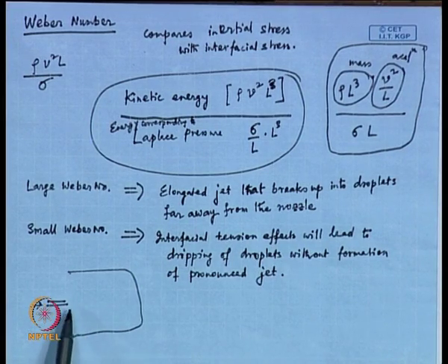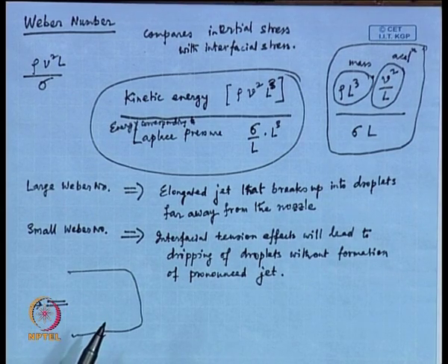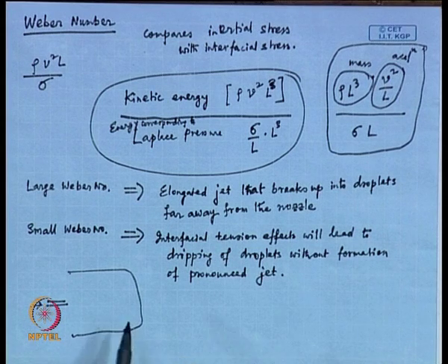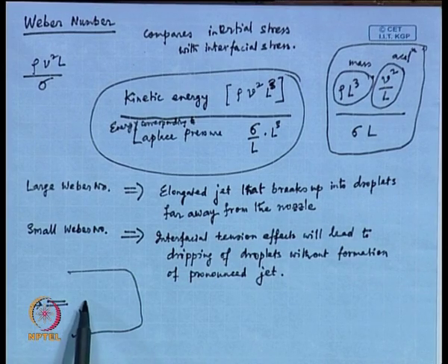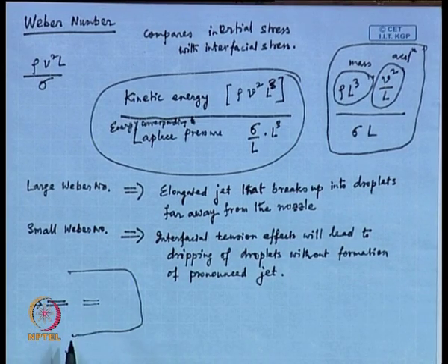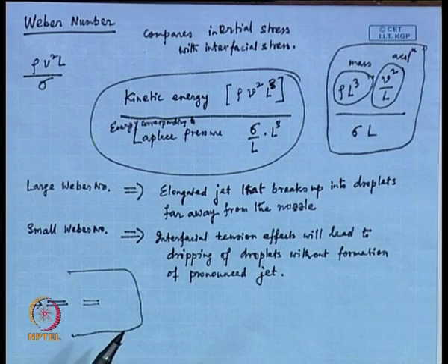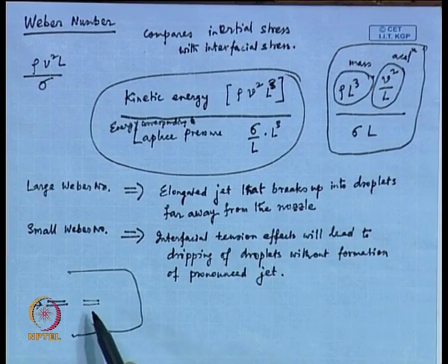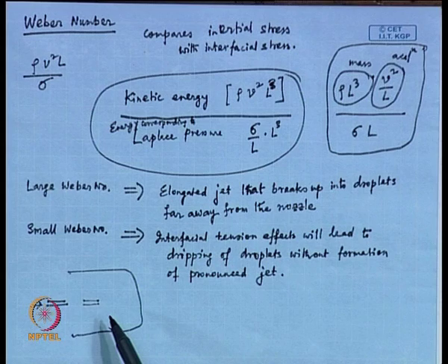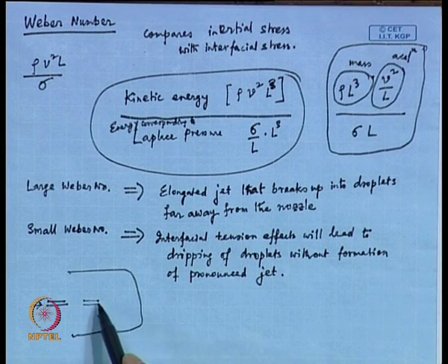That would be in the form of some tube inserted into that pool, and then you are forming droplets or bubbles, because the moment you are introducing a flow, you are introducing a cylinder. If there would have been no other obstruction, the flow should have continued like a cylinder, but due to instability, this cylinder cannot continue that way. Instead, this cylinder breaks down.